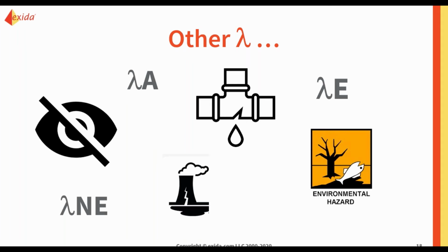The process can still be taken to the safe state if needed. But it is good to be aware of these no effect failures, especially if you have a very dangerous or hazardous process. Some no effect failures could be external leaks or small internal leaks, display issues, a bolt loosening, or maybe one of 12 bolts breaking off. So they're good to be aware of, but it's not something that will prevent the valve from closing at the end of the day.